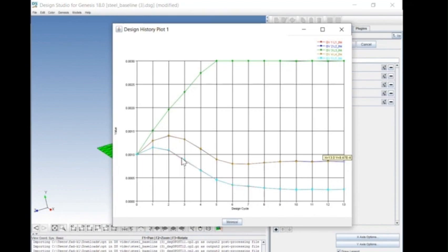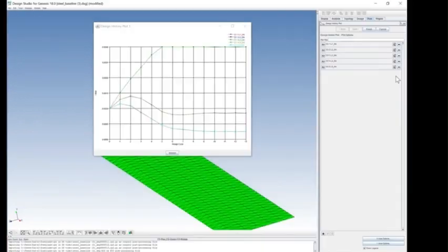And then we've got these here. You can just about see we've got the cyan one and the red one. So those are the plies at -90 and at 90 degrees. They start off at 1 mil thick and they go down to a minimum, or down to this value here, 0.251 millimeters thick. Okay, so we can see how the thicknesses of each of the variables change over the optimization. Now, the history file is just a text file, and that will tell us how the design variables have changed over each design cycle. It will also tell us how the objective and the constraint have changed over each design cycle. So let's now open that and examine that.